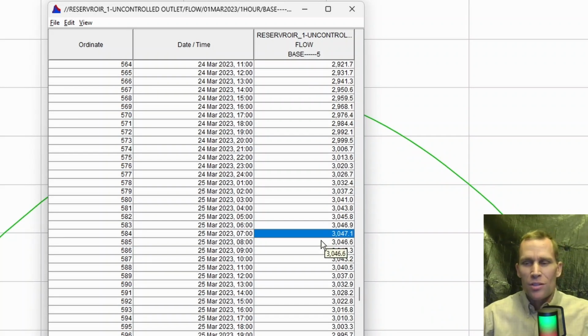But this problem was just academic in general to kind of understand what sort of problems we may want to solve in the real world, and also how to use ResSim to help us get to those results. So what we did here is we used ResSim, specifically the Monte Carlo analysis tool, the Monte Carlo alternative type, to create a population of different values for that maximum release through the controlled outlet as a way to more quickly evaluate the system and find a specific solution, like we did here with what is close to the correct solution in this final trial here.